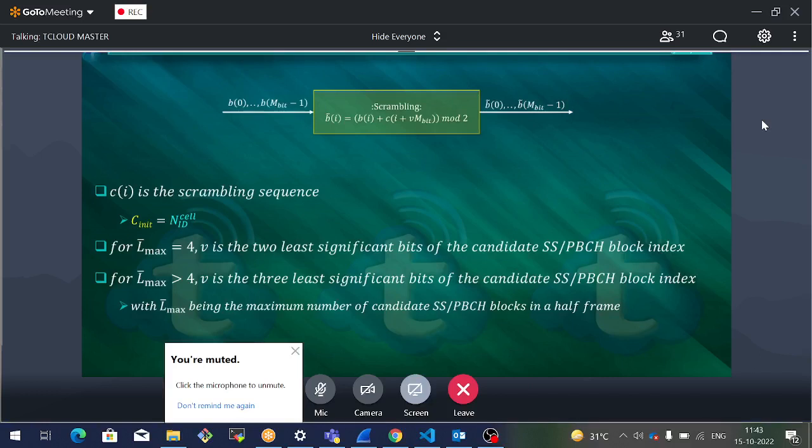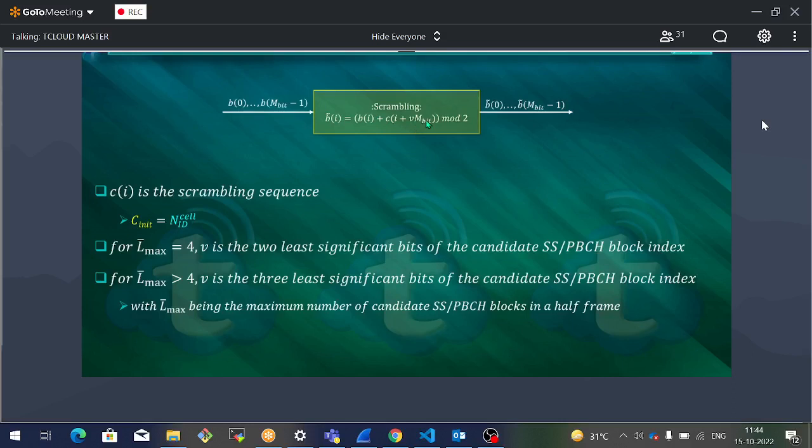And for the M number of bits that you want to compute, you take that M bit number also into this equation here. And then from that, you do the cyclic shifting of this scrambling sequence. Remember, anytime you have a scrambling sequence which contains an additional input, you have to consider that the calculated scrambling sequence will be cyclic shifted by this unit. For example, if v of M bit total value is 8, let us suppose, the scrambling will be from the 8th bit for the 0th element. When i is 0, the scrambling bit which we have to take is the 8th bit, because this vM bit is 8, even though i is 0.